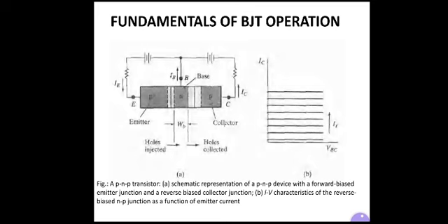Here the current in such a junction is due to the holes that are injected from the P plus region into the N material. If we make the N side of the forward bias junction the same as the N side of the reverse bias junction, then the P plus NP structure, as shown in the figure, will be the result.